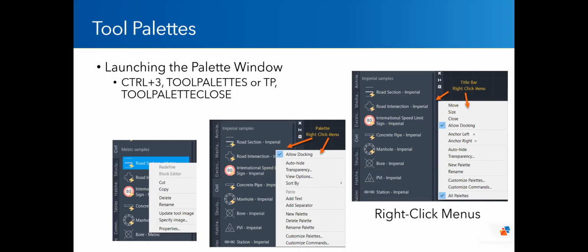So that will load the default tool palette in your AutoCAD. If it's out of the box, then you get one tool palette coming up with a bunch of different tabs. You're going to find a collection of hatch patterns and blocks based on industries.